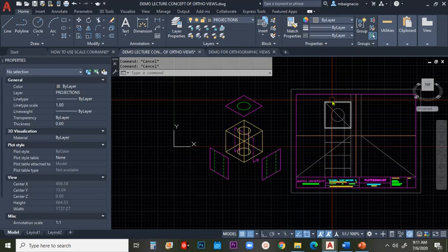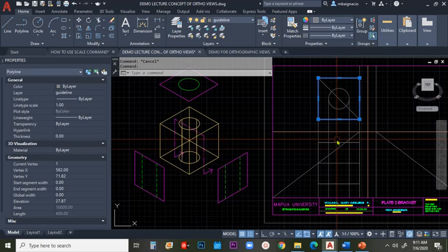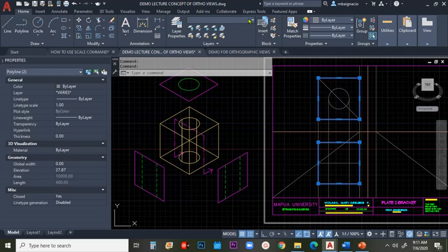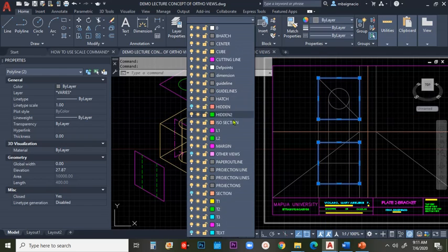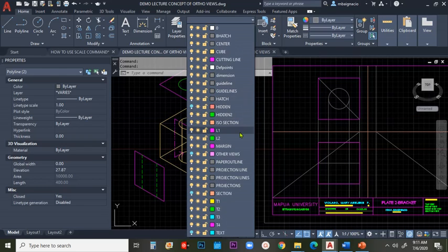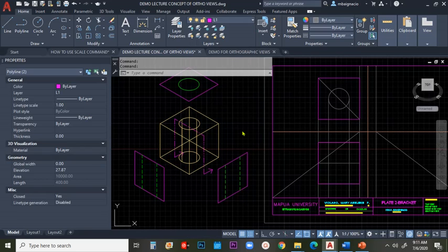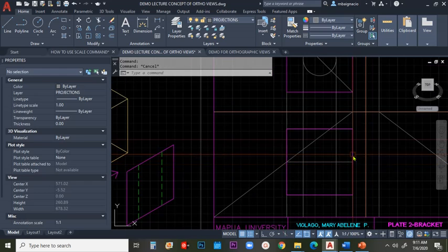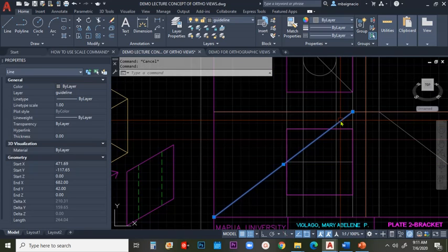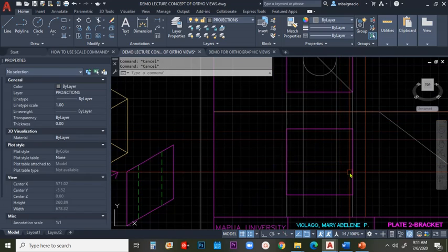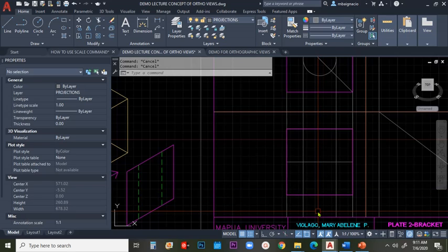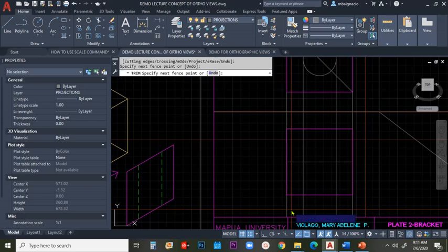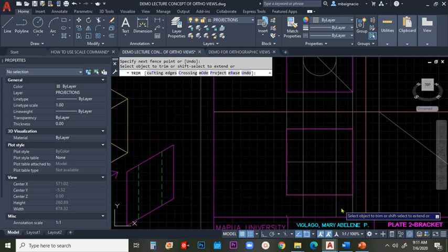Now maybe I can replace already the layers for this, since we have already incorporated. So I'll make use of L1 to be the thicker lines here. Okay, so next I will be removing the diagram of this intersecting point for our insertion point, and then I'll trim down all the excess lines below.